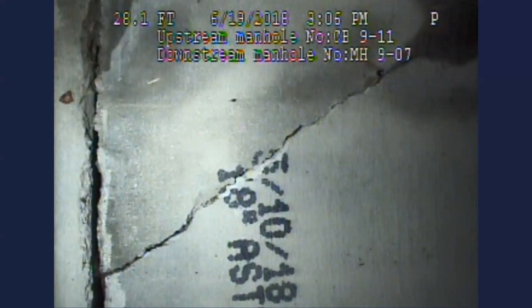Typically, this happens when a gasket wasn't equalized or it was loaded too much as they put it in. Maybe the gasket slipped and moved as they didn't put it in completely straight, so it wasn't homed correctly, and then it caused enough pressure and buildup in the bottom of the pipe as they were homing it that it just popped this bottom part of the pipe out. And so this could be a problem functionally. Structurally, it's actually a pretty minor crack.